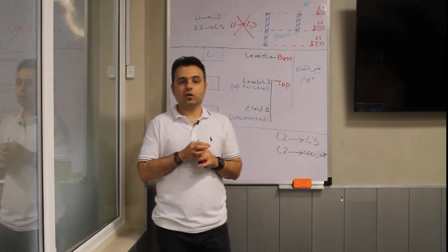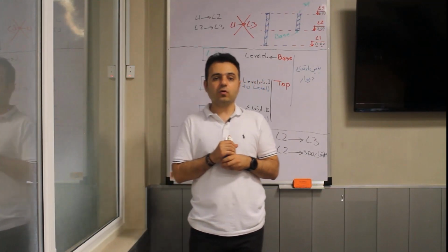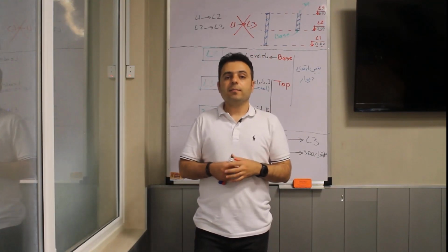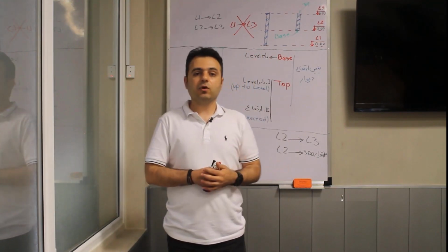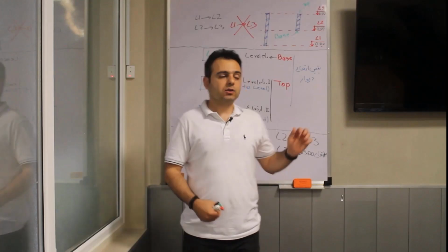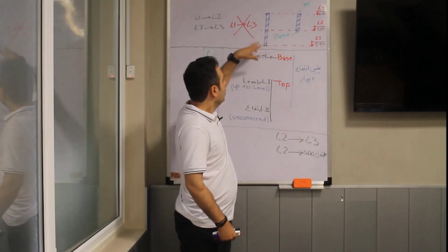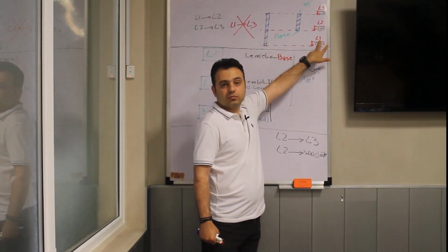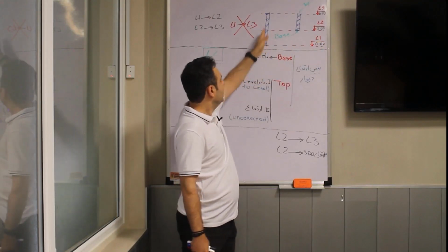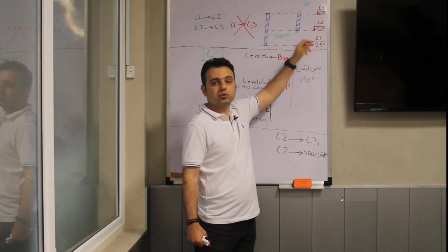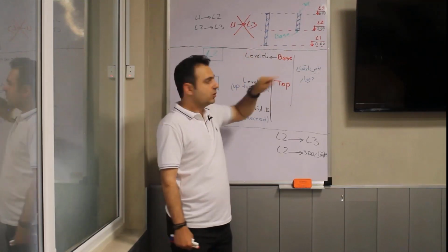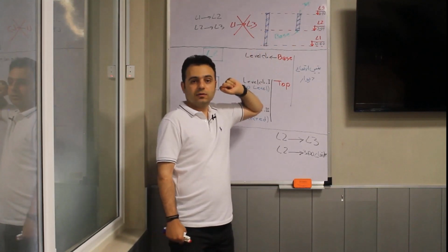This is the first reason, but another reason is that if you draw the walls flatly, you will not have the size of the walls in each floor. If you draw this wall flatly, it shows you all the volume of this wall in the first floor, just the first floor. But why? Because Revit counts the wall based on the floor they have started from.